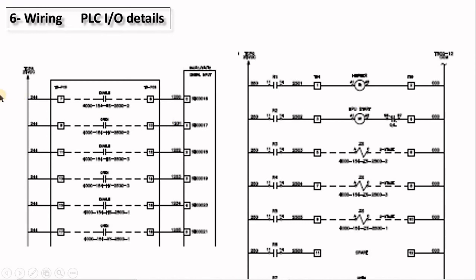If you have a digital input, it will be exactly the same. This is my digital input. This is field wiring, and this is the supply, let's say the 24 volt or 120, goes to the contact in the field and comes back from the contact to your card here.